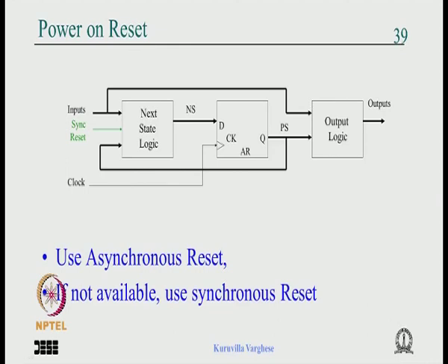And when it comes to the VHDL, we will go back to the VHDL coding of the state machine, though it is nothing great, because we know how to code flip flops or registers. We know how to code the combination circuit, because this is a combination circuit, and this is a combination circuit. We have seen that you could combine the output logic with the next state logic, but after all it's a combination circuit and we know how to code it.